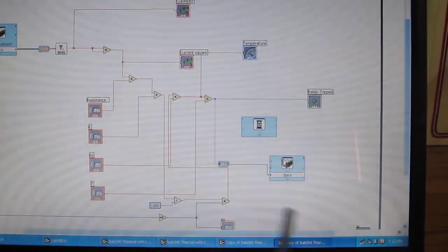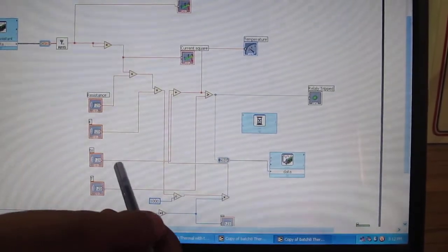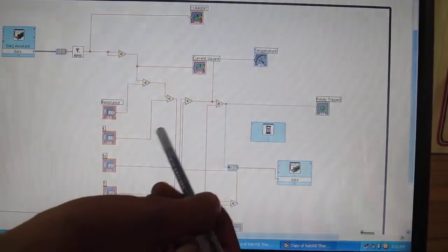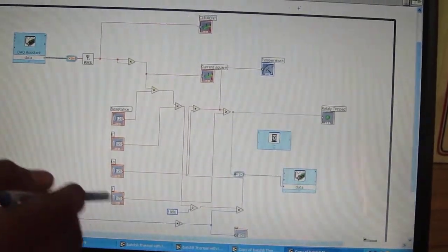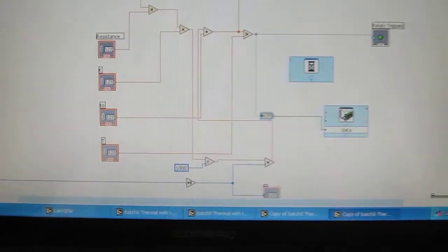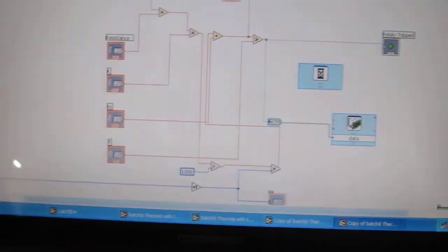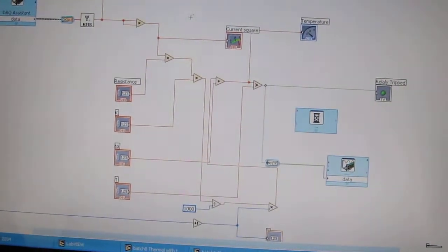Like 26 degrees centigrade or 27 degrees centigrade. I am going to add this initial room temperature to the actual winding temperature. Here the capital T is nothing but the actual safe value of working temperature for the motor. Here the motor safe working temperature is given with ambient temperature as 40 degrees centigrade, so I kept the safe limit as 40 degrees centigrade.